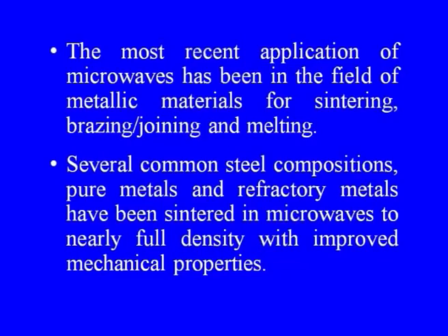The most recent application of microwaves has been in the field of metallic materials for sintering, brazing, joining, melting and cladding and so on. Several common steel compositions, pure metals and refractory metals have also been sintered in microwaves to nearly full density with improved mechanical properties. Why the mechanical properties could be improved, that I have already indicated.